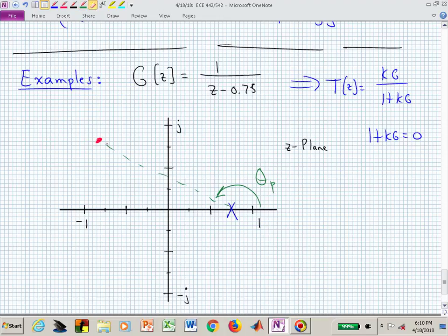You had already told me with your looks, you gave me the look this time, that the root locus was there. That's the only potential closed loop pole locations for proportional control. And what you do is live on that line. And you know how big K can be before you go unstable. If you crank up the gain to get beyond that point, you've gone unstable.